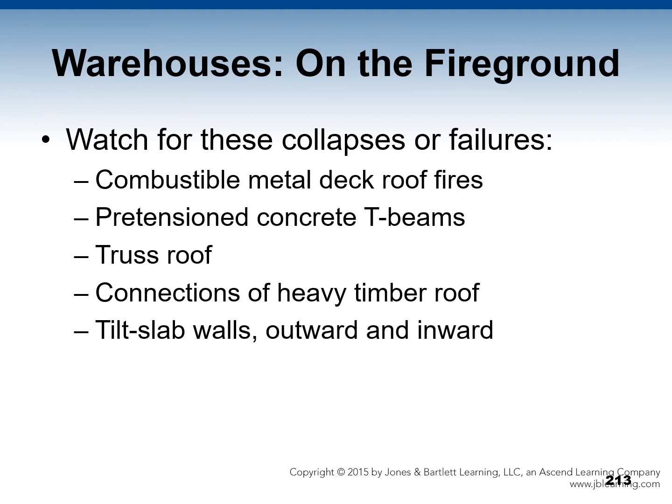At a warehouse where there is a fire, you need to watch for these types of collapses or failures: a combustible metal deck roof fire, pretension concrete T-beams, truss roofs, connection or splices of heavy timbered roof, tilt slab walls outward and inward.